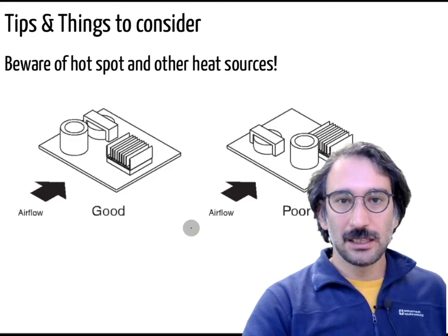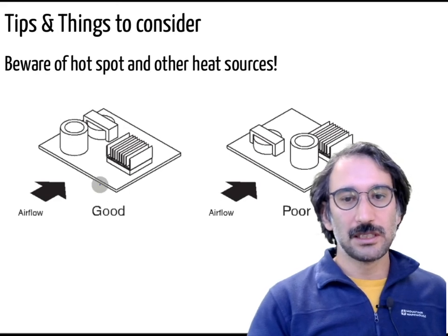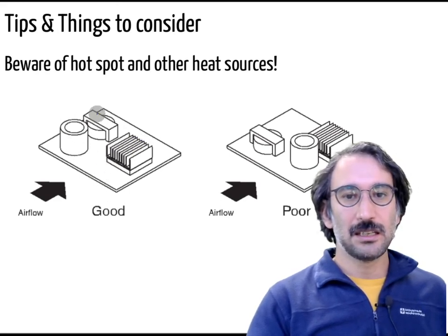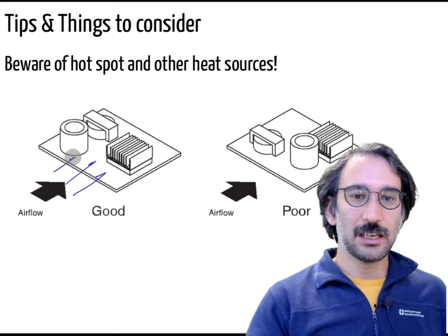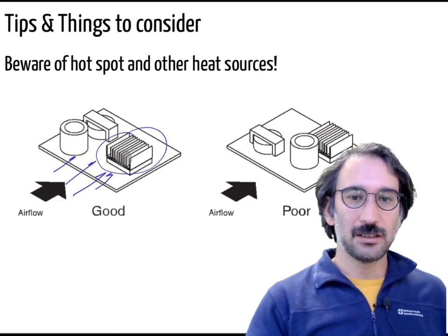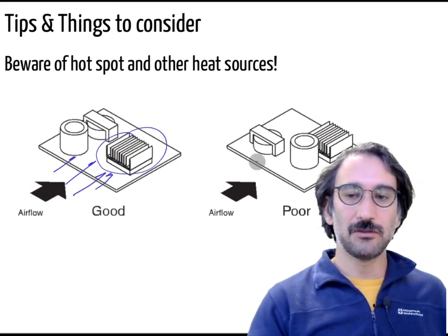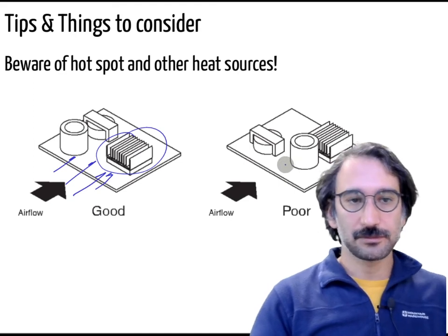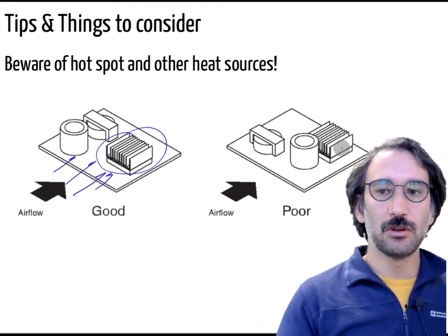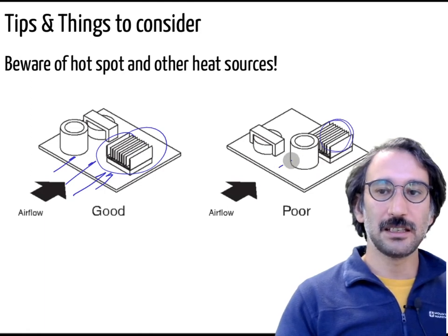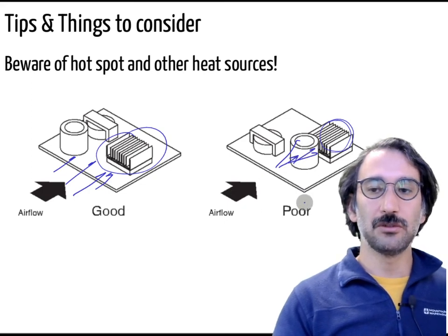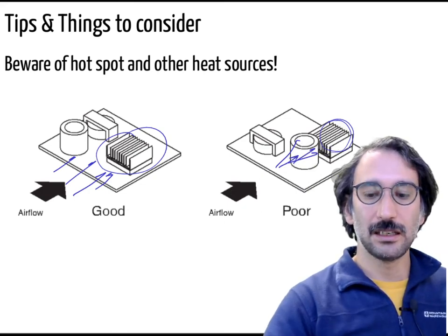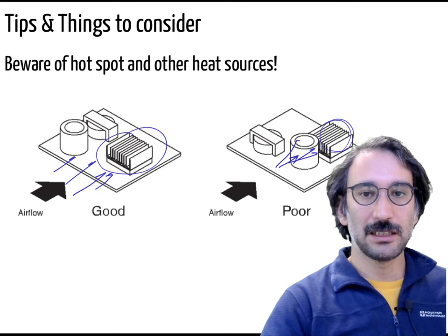And the other one is the layout. For example, here you see a heat sink and you have other capacitors or inductors, and this is your main heat sink. If your fan is blowing air in that direction, here it is completely open to airflow, but on the right-hand side, your heat sink is blocked by some components, so it will not get that cool airflow over the heat sink, and you will not get good performance from that layout.